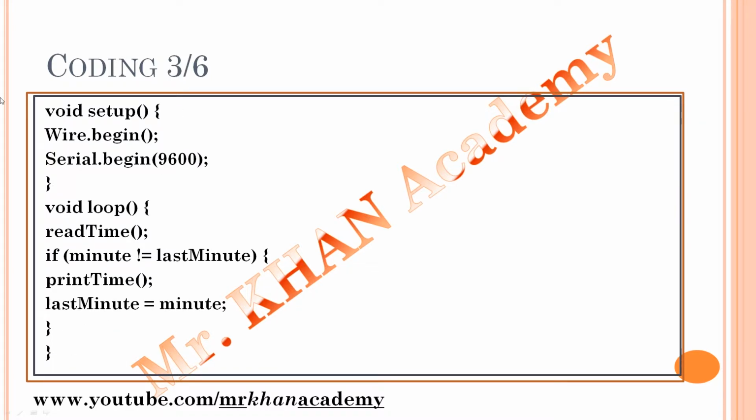Now next, part 3, we are using the void setup and void loop functions. In void setup, as we are using two communications, wire communication and serial communication, I'm starting Wire.begin, and after that Serial.begin. The RTC data is sent to the Arduino using wire communication, Wire.begin, and from the Arduino to our system, on the monitor display, with the help of the serial monitor. For that we are using serial communication, so I define Serial.begin, and the data rate at which it is transferring the data is 9600. If you want to learn more about serial communication, you can watch my 10.1 part. This is all about the void setup.